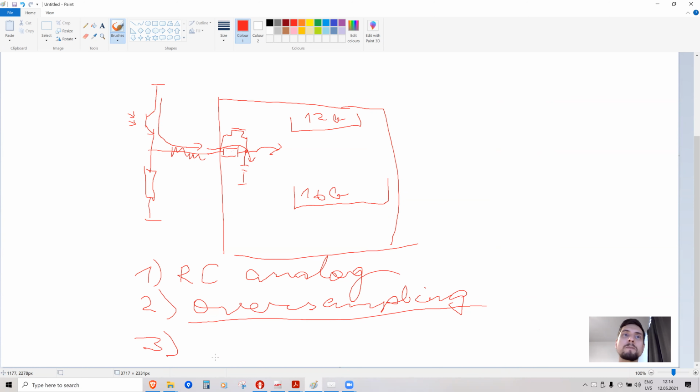And the third one is removing the top and bottom value to remove some spikes. Let's say you have some samples, but during one sampling there was some mistake, which was a small spike. Now, if you calculate the average of 16 points in this case, even though this was some glitch, it moves the average up. And the same goes if there was some glitch and one sample was way off to the bottom side, it would move the average down.